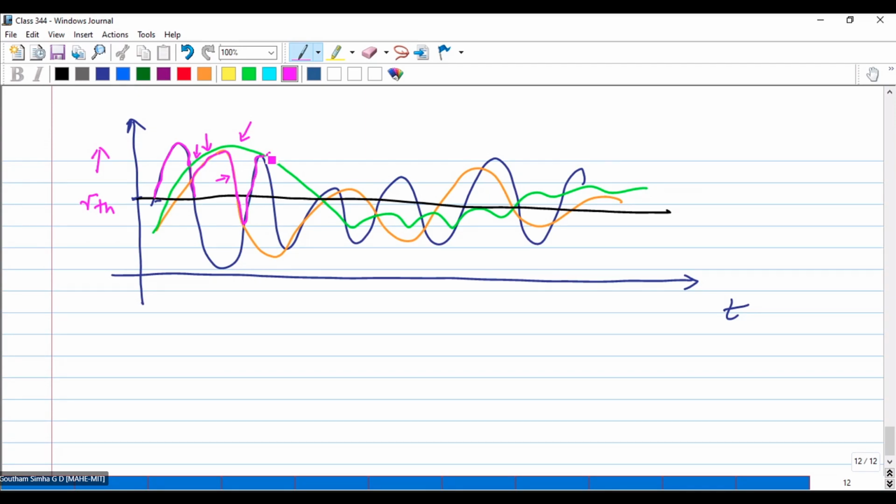Then instead of switching to the green, I'll follow this because this is at higher SNR. Switching and staying is nothing but switching at higher SNR thresholds. If the signal is not going below the threshold, and if another branch comes in between which is higher than the highest threshold already available, don't switch unnecessarily.